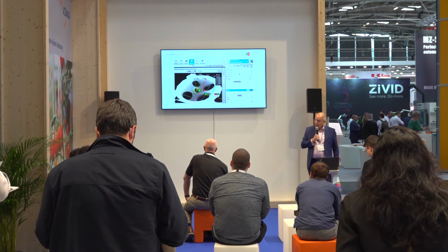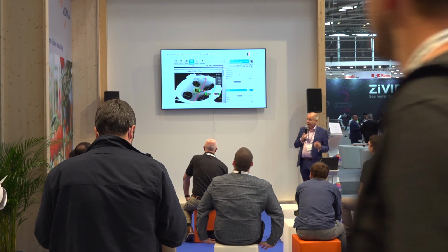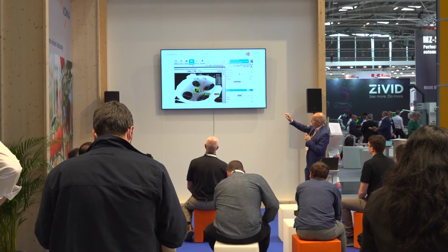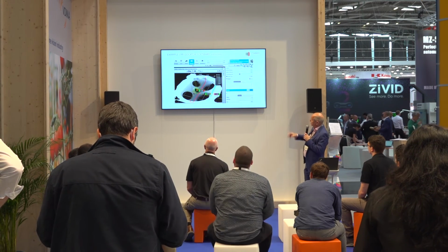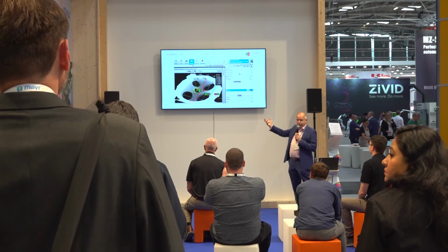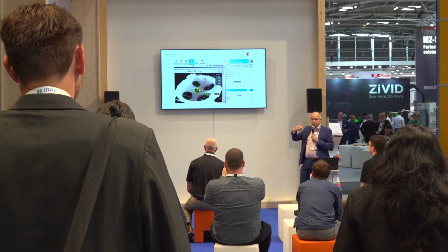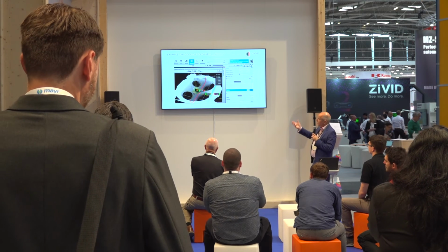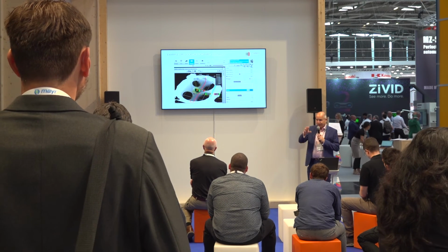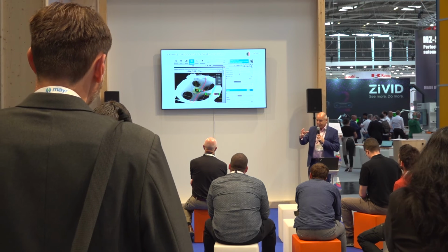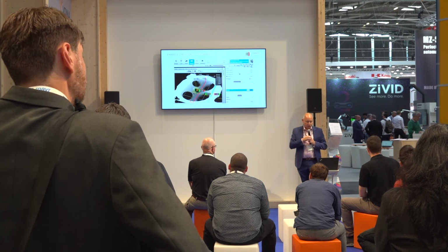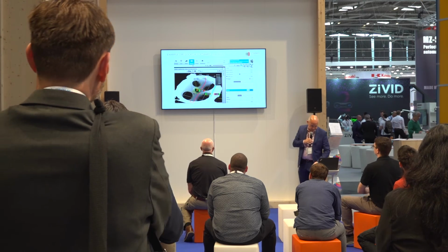This is a picture of the user interface on the LMI web browser. So you have a big list of tools, literally drag and drop, mark the points you want to do, connects with the PLC directly, connects directly with robots such as Universal Robots, Fanuc and people like that. So you don't even need a PC to get that data, calibrating very easily the 3D map of the camera into the 3D space of the robot.